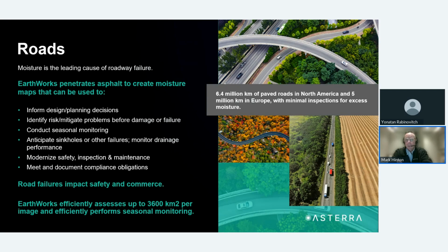And a point to mention here, I did mention earlier that increasingly climate change models, when added into traditional geotechnical asset models, are showing a distinct acceleration in the deterioration timescales of geotechnical assets. So interventions such as additional or better maintained drainage, as an example, can successfully extend an asset life cycle, which is a real return on investment case. And provided the monitoring is proactive and the actions are well targeted, you will get real benefits.